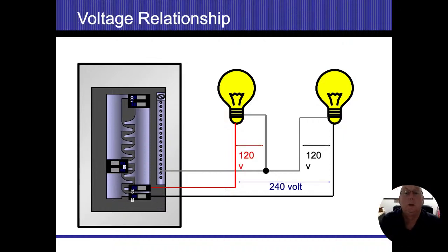Between the two connections, we have 240 volts, but because I connected the neutrals on there, that's going to keep both of those at 120 coming in there. So if each one of these light bulbs is 120 watts, that means each one of these light bulbs is going to allow 1 amp of electricity to flow. 1 amp is going to go into the light bulb, each one of these. 1 amp is going to come out of the light bulb on the neutral, each one of these. When I get to that little black dot on there where they meet, now I'm no longer going to have any amperage flowing down that wire. They're both going to cancel each other out, and then we're going to end up having 0 amperage from that point forward.